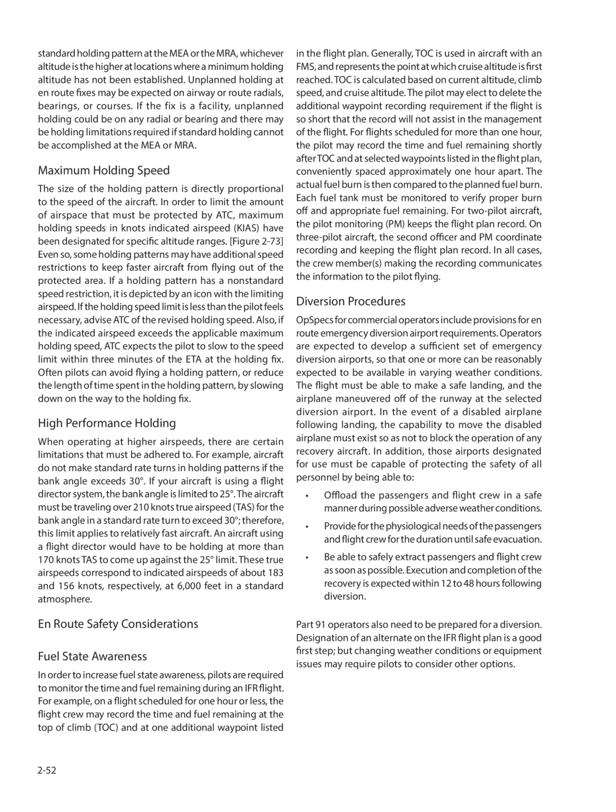In addition, those airports designated for use must be capable of protecting the safety of all personnel by being able to offload the passengers and flight crew in a safe manner during possible adverse weather conditions. Provide for the physiological needs of the passengers and flight crew for the duration until safe evacuation. Be able to safely extract passengers and flight crew as soon as possible. Execution and completion of the recovery is expected within 12 to 48 hours following diversion. Part 91. Operators also need to be prepared for a diversion. Designation of an alternate on the IFR flight plan is a good first step, but changing weather conditions or equipment issues may require pilots to consider other options.